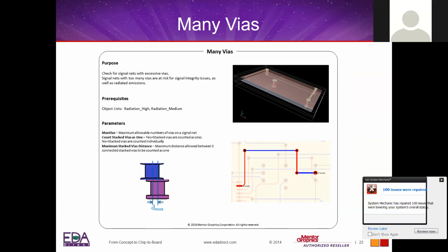And why did that happen? Well, they were routing and they hit a bottleneck, can't route anymore, so they jump off into the power plane or the ground, route over the congested area, and then come back down. That added some vias into the address line.